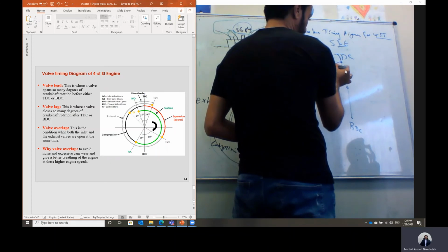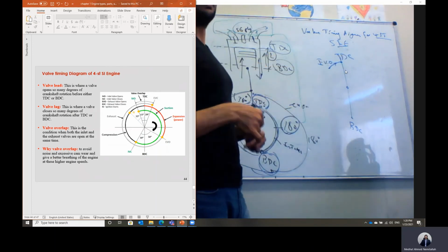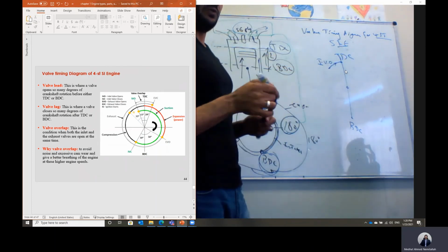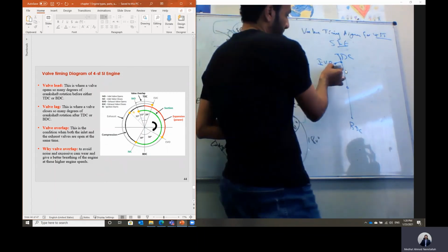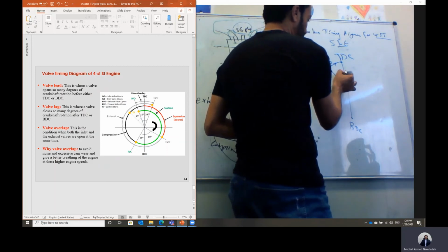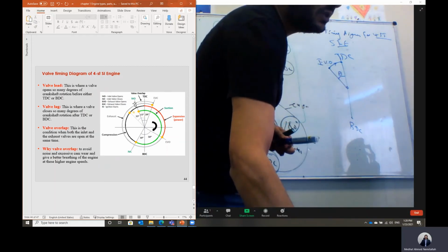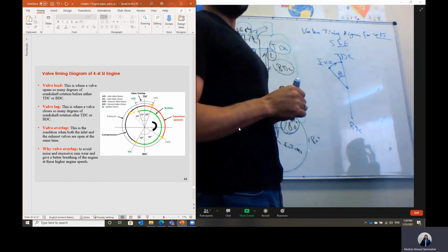Usually, during the rotation of the crankshaft, the intake valve is opened before the piston reaches the top dead center, while still in the exhaust stroke. So before we start the suction stroke, the intake valve will open at a certain angle of the crankshaft. This angle, you can see here, is about 15 degrees, in which the intake valve opens before the piston reaches the top dead center.